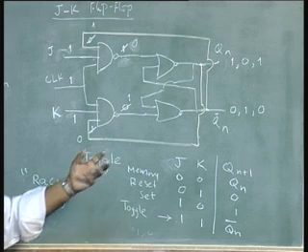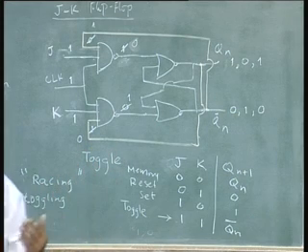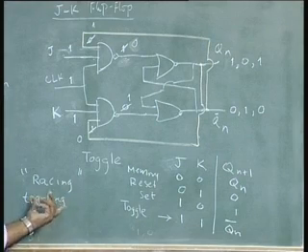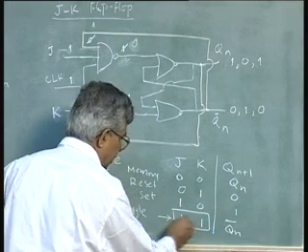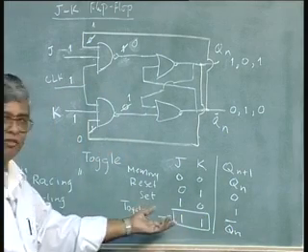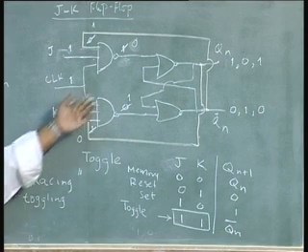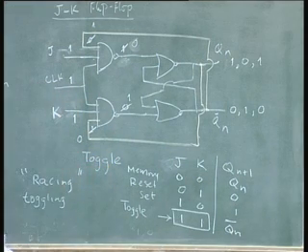That means I need to operate with a very, very high clock, which is not possible and also not required. So, I should have some other way of controlling the toggle. I need this desirable condition of 1 1 as a toggle condition, which is an improvement from an SR flip flop. On the other hand, I do not like this racing, where the output keeps changing.